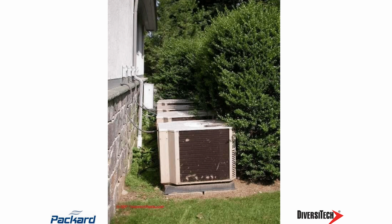And look how close those units are. That's going to affect my static. It's going to affect the amount of air that I have on that. And I could see an increase in my amps as a result, and again, a reduction of air. And these are things that you typically run across.